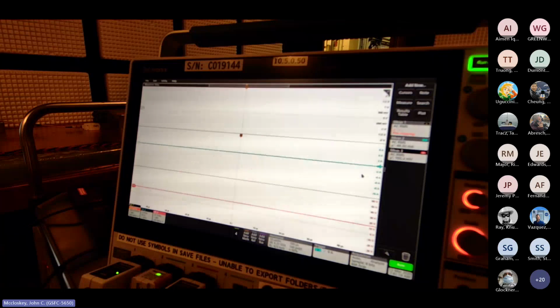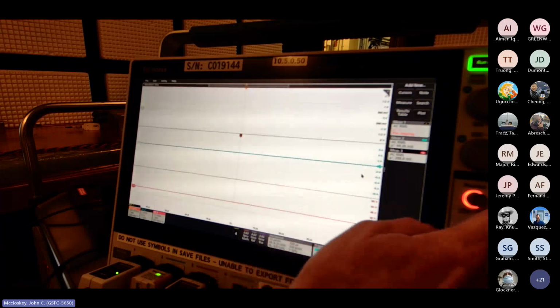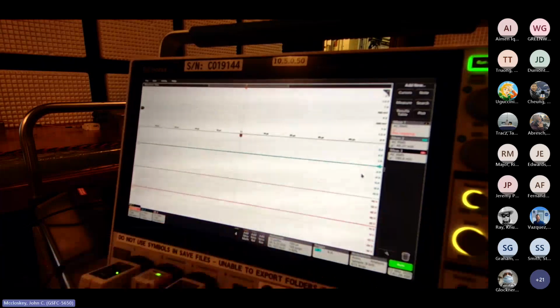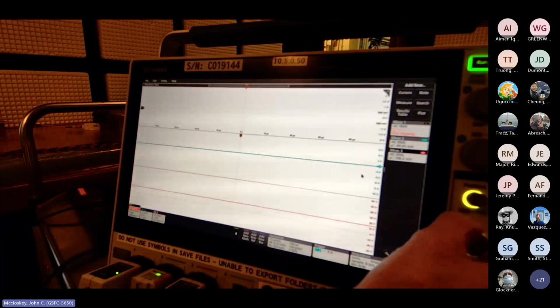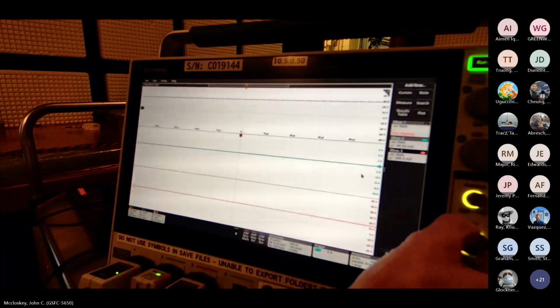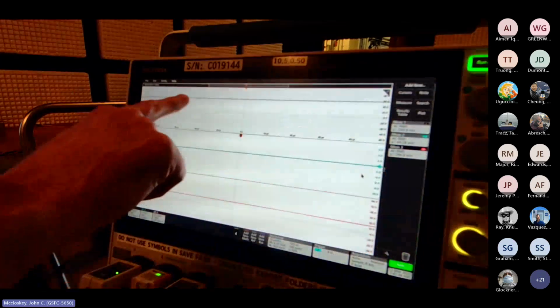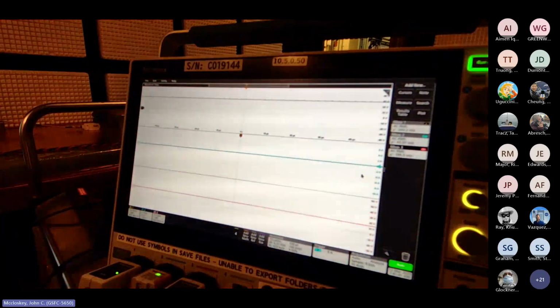The top trace went off the screen, right? Because it was centered around 0. For pre-cal, we were centered around 0, just going across the resistor. But now we're riding on top of the 28 volts. So now we've got to find our signal. And so again, I don't want to AC couple, and we're not going to do that. But so we collapse our scale. All right, now we're at 10 volts per division. So there's our signal. There's our DC level.